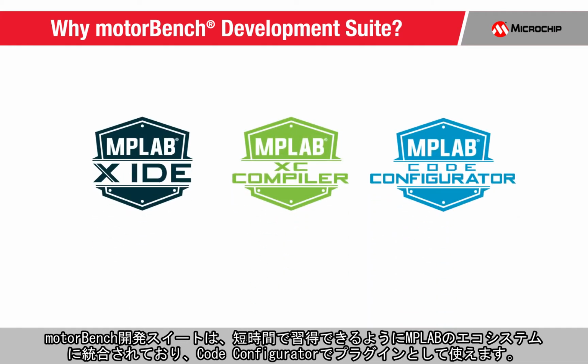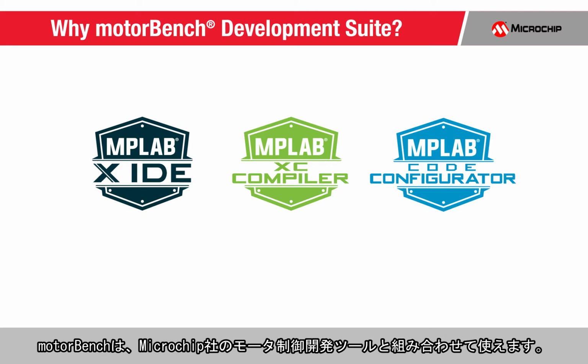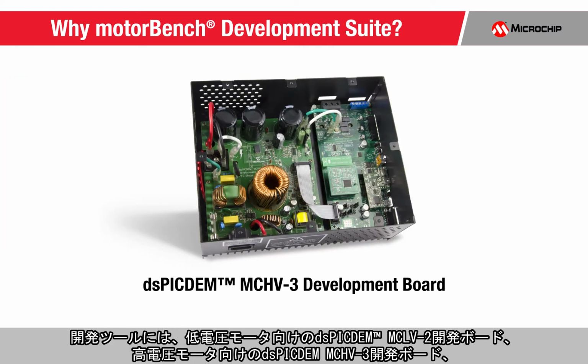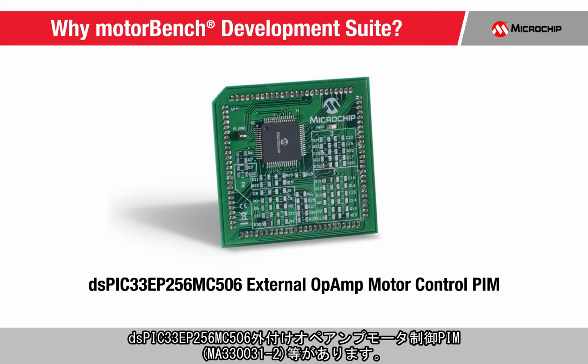To reduce your learning curve, the motorBench development suite is integrated into the MPLAB-X ecosystem and is available as an MPLAB-X IDE plugin within the MPLAB Code Configurator. It works in conjunction with Microchip's motor control development tools like the dsPICDEM MCLV2 development board for low voltage motors, the dsPICDEM MCHV3 development board for high voltage motors, and the dsPIC33EP256MC506 external op-amp motor control PIM.